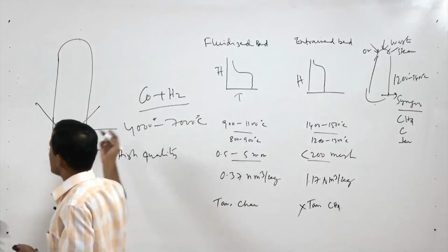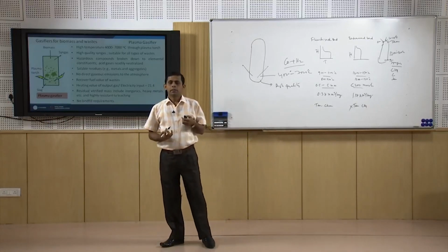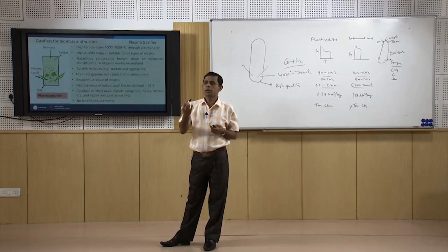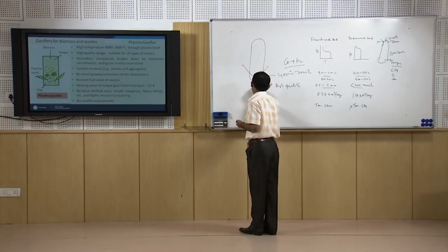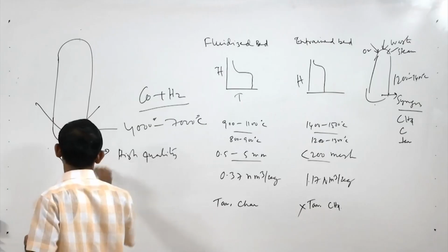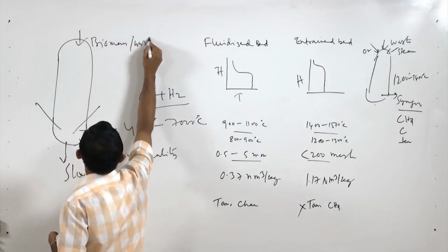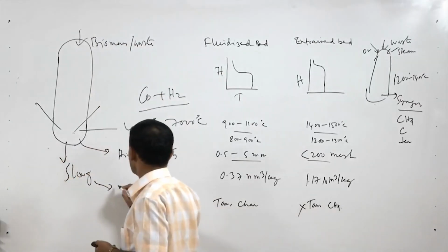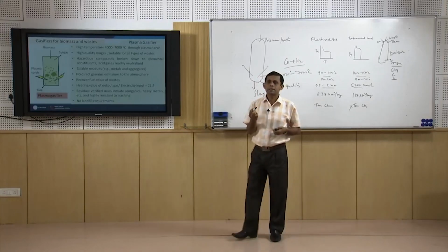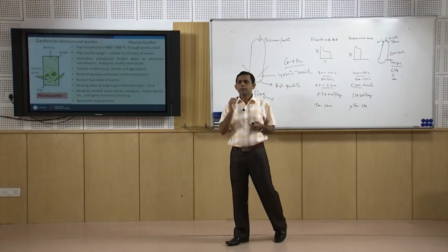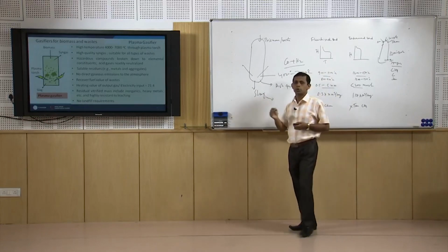Why high quality? The high temperature helps to neutralize the acid gases. This high temperature also helps to convert all the metals in ash to their metallic form. So, the slag which is formed here is in pure metal form, or this material has very little leaching property. So, nothing is leachable here. So, the management of this is easy and it can be directly used also.